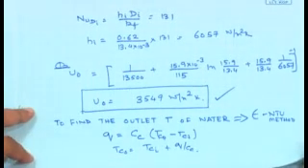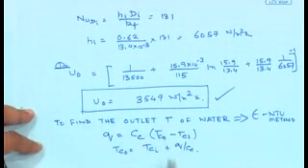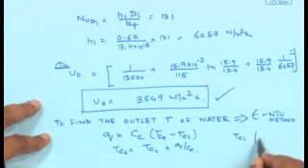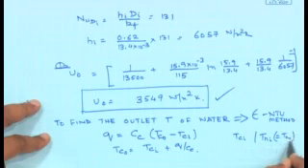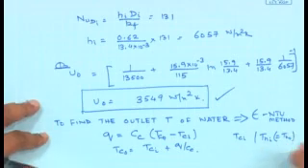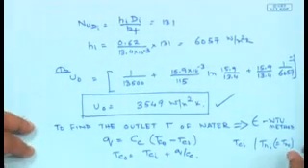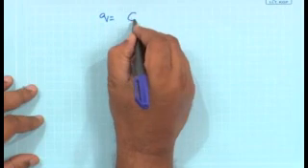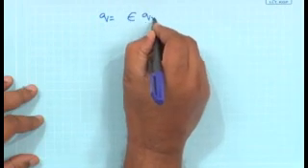Now this Q is to be obtained. So this is the outlet temperature, but I do not know the outlet temperature. I only know the inlet temperature. So TCI and THI, which is equal to THO, this is known to me. So how do I do this? My Q, the total amount of heat transfer, would be effectiveness times Q max.